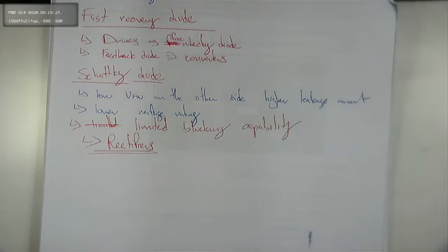Now, what about diode protection? Everything needs protection from something, right? Diodes also need protection. Now, what do you think? How can we protect a diode? In general, what do we use? We use a semiconductor fuse.